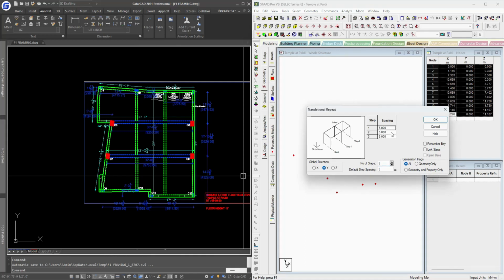Let us say plinth level is at... it will be a structure with piles, so plinth level shall be just 300 mm down from the ground level, and pile top level and plinth level shall be at 750 from the ground level. So our distance shall be 750 plus 300, that is 1.05, the first step.